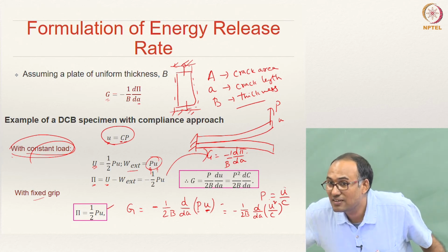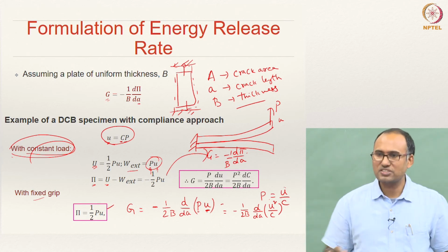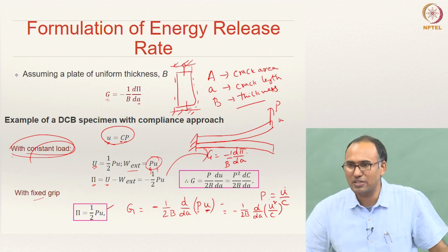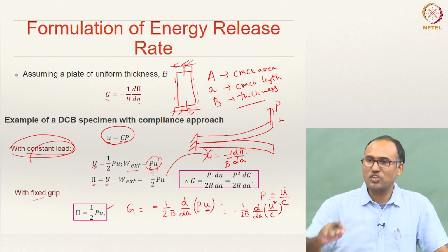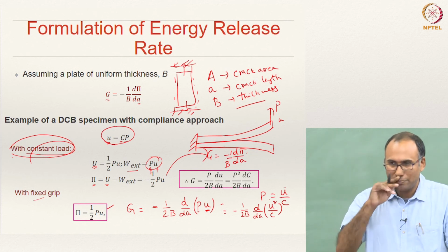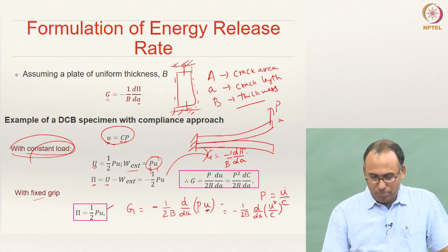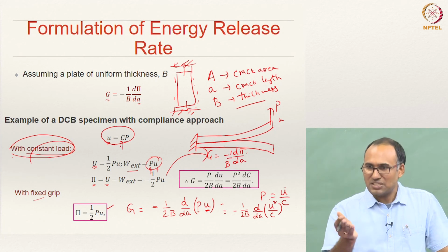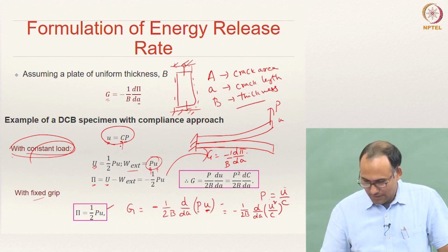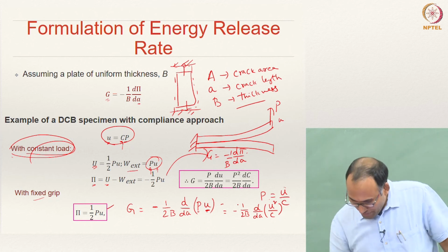What is compliance? Compliance is opposite of stiffness. Stiffness is force per displacement, right? Compliance is reciprocal of that. You can see here, C is your compliance, right? C is displacement by force. Alright. So, now what will be this one?